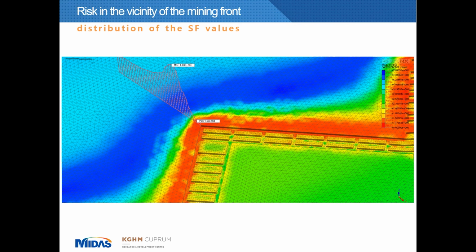And again, numerical modeling with the use of GTS NX software can play an important role in the process of minimizing the geomechanical risk in the vicinity of the exploitation fronts. If the excavations of the rock mass are modeled with the use of appropriately dense mesh, then it is possible to determine the distribution of the pressure zone in the vicinity of the excavation, and of course to determine the potential location of the maximal stress that we want to target with our distress blasting.